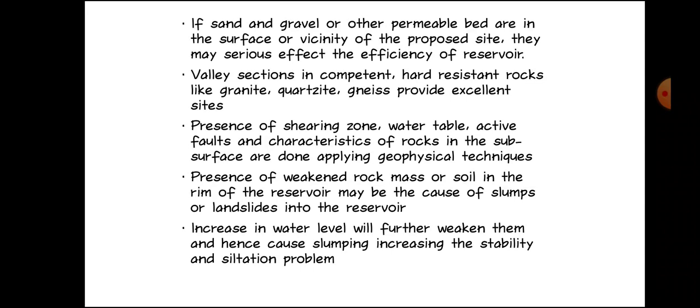Presence of weakened rock mass or soil in the rim of the reservoir may be the cause of slumps or landslides into the reservoir. An increase in water level will further weaken them and hence cause slumping, increasing the stability and siltation problems.